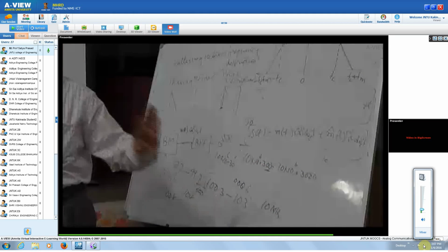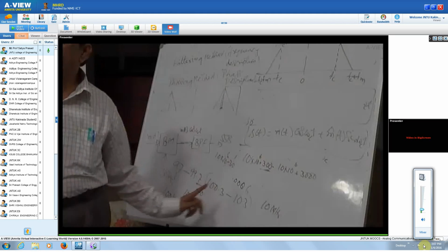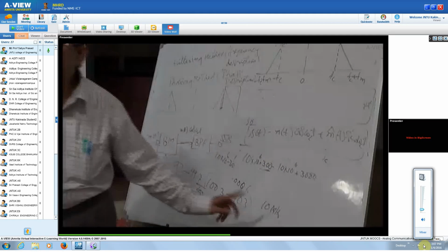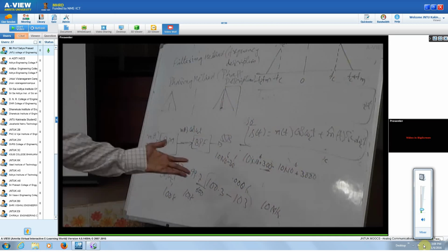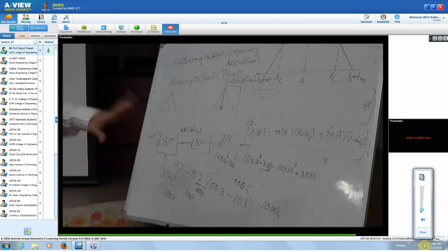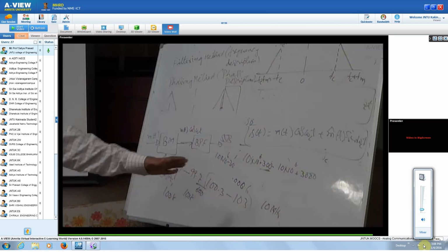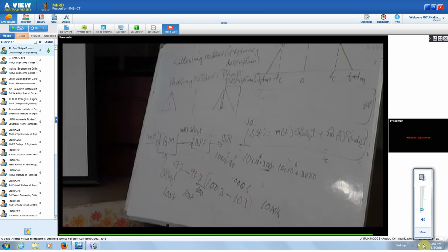That means the band difference is 200 kilohertz at a 10 megahertz carrier frequency. Therefore 0.2% is the cutoff frequency variation that we are going to have, whereas previously we had 0.0006. Therefore you can't design that, but this you will be able to design.